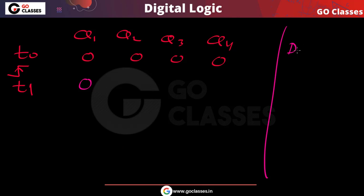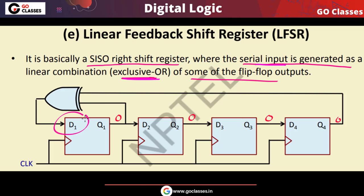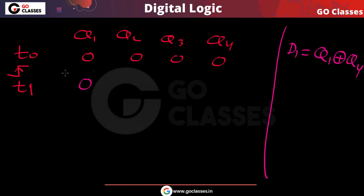You can notice that D1 is basically Q1 exclusive or Q4. So after one clock pulse, this Q1 exclusive or Q4 is 0. Because D1 is equal to Q1 exclusive or Q4, D2 is simply Q1, D3 is simply Q2, and D4 is simply Q3.